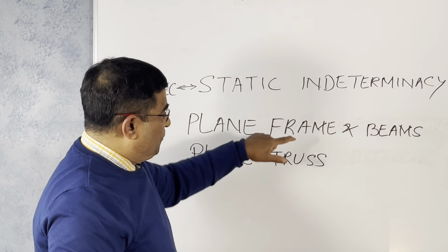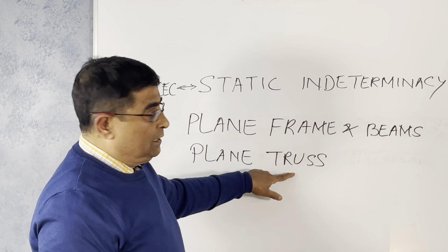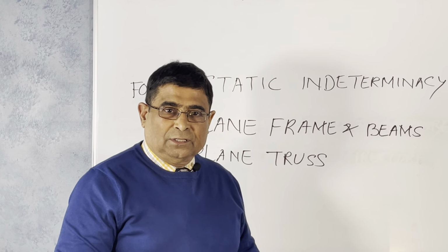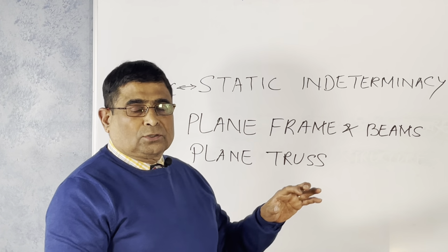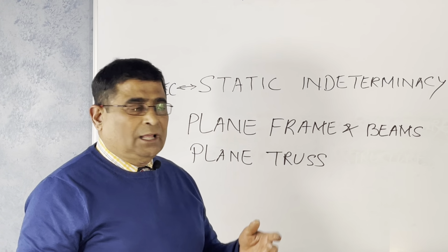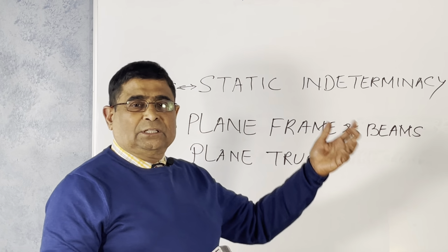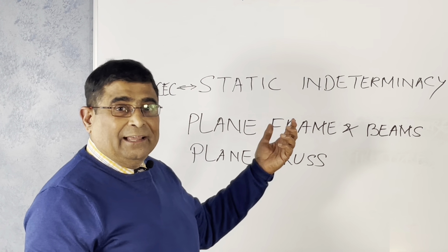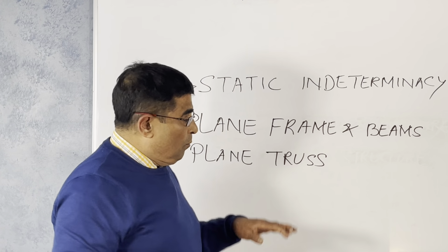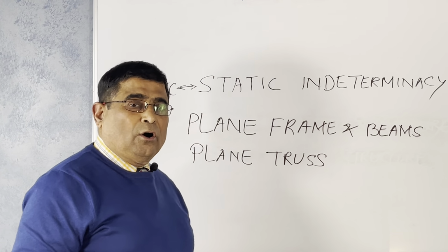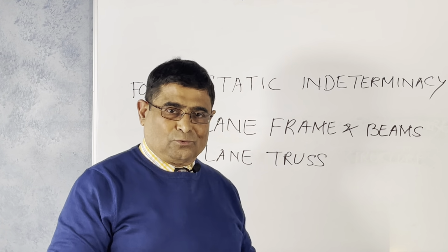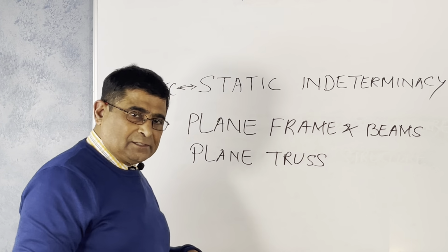You know the difference between the frame and truss, right? In the frame you can have moment, shear, torsion. Torsion can be considered also, but our focus is the axial forces, moment, and shear force. The plane truss has only axial forces, tensile force or compression force. These are the two forces on the plane truss.